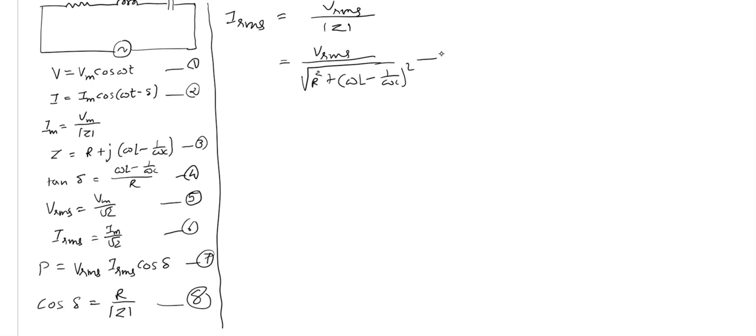It means that if you want to change IRMS, apart from the source, the options which you have available are resistor value, inductor value, capacitor value and omega. So if you don't change component, that is R, L and C, still if you change omega value, angular frequency of the source, then also IRMS can be changed.